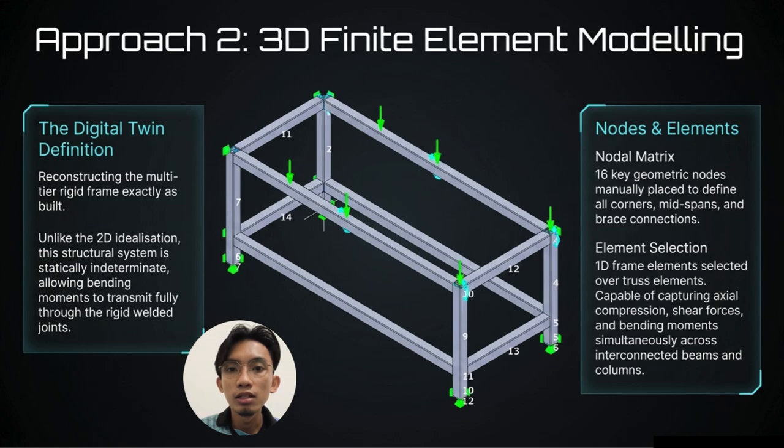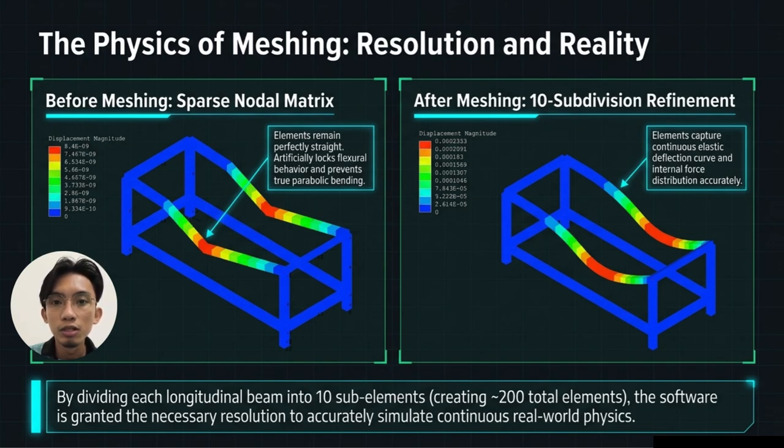So while the analytical calculations provide a useful baseline, they simplify the structure into a single beam. Therefore, a three-dimensional finite element model was developed in LISA software to capture the actual frame behavior and load distribution within the structure. This slide shows the finite element model developed in LISA software. The geometry was created using the measured dimensions of the actual table. Material properties, loading conditions, and support constraints were assigned to replicate the physical structure as closely as possible.